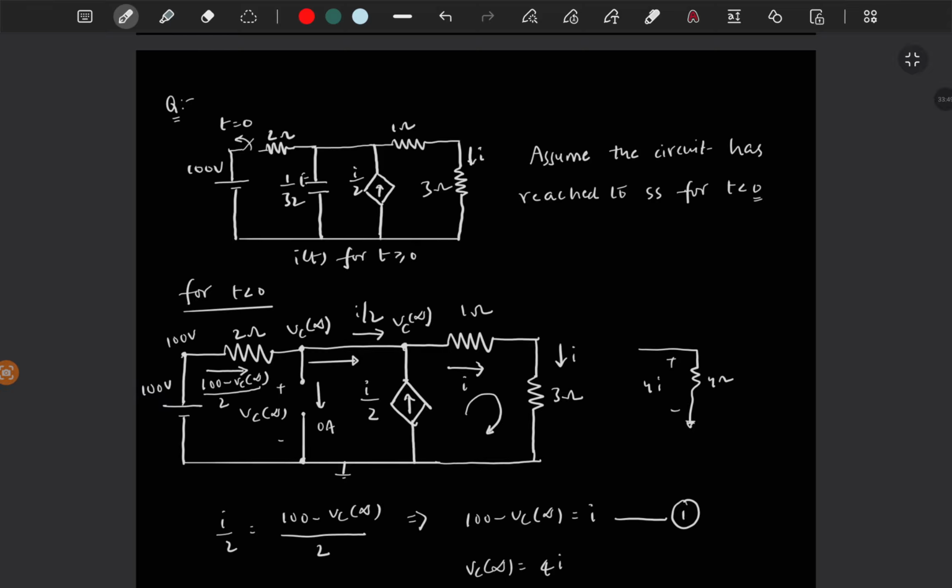So since it is a first order circuit, my suggestion is to find first the voltage across the capacitor. Whatever the current or whatever the voltage is given to find in the question, doesn't matter. You have to find the voltage from there, because this is simpler, right?